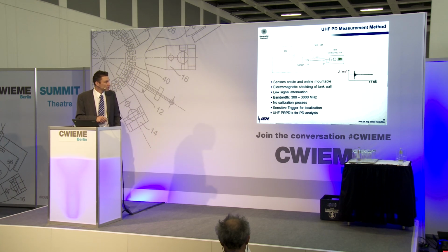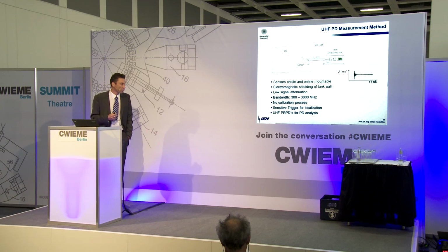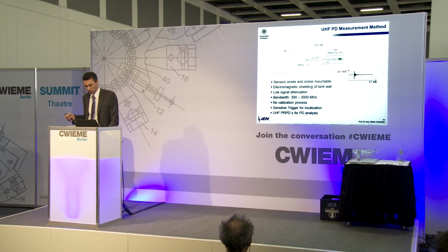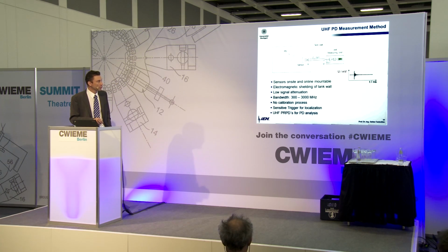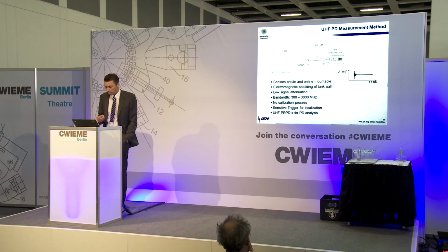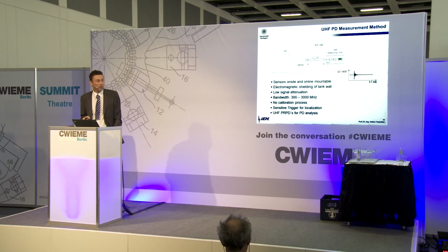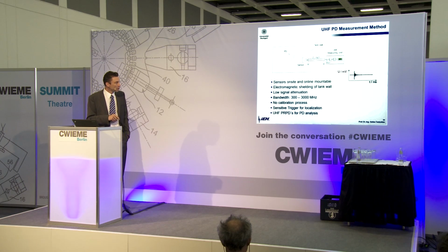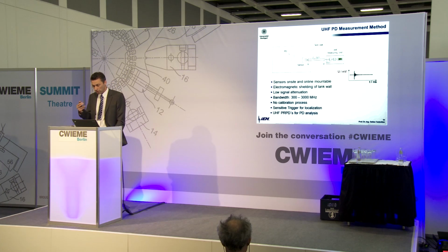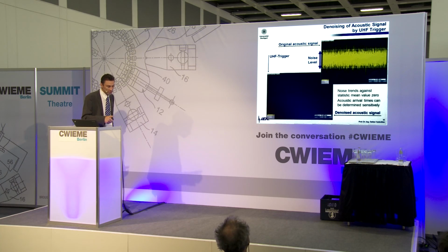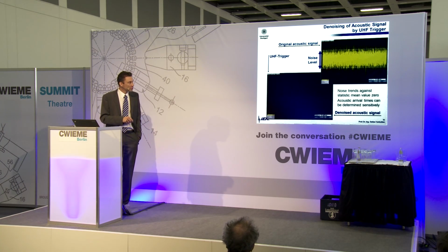Furthermore, because this signal is very sensitive for PDs, you can use it for triggering the acoustic signal. So you connect this antenna to the trigger input of your oscilloscope. The measuring channels are connected to your microphones, and once you receive a signal from the sensor, you also measure the output of the microphones. This is shown in this slide. So once triggered, you measure this output signal